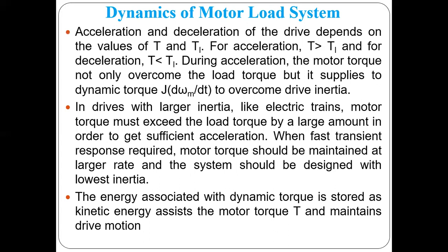According to this equation, the acceleration and deceleration of the drive depend on the value of motor torque and load torque. In case of acceleration, motor torque is greater than load torque, and for deceleration, motor torque is less than load torque. During acceleration, the motor torque not only overcomes the load torque, but also supplies the dynamic torque, that means J d omega upon dt, to overcome the drive inertia.